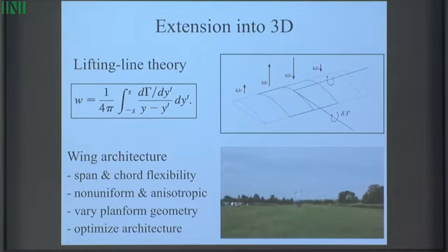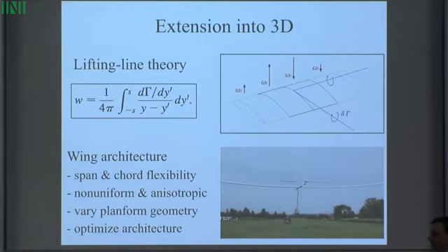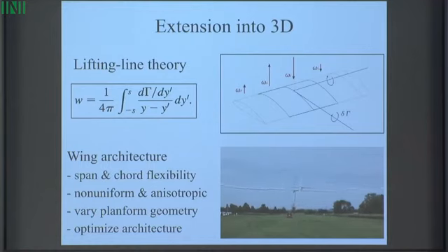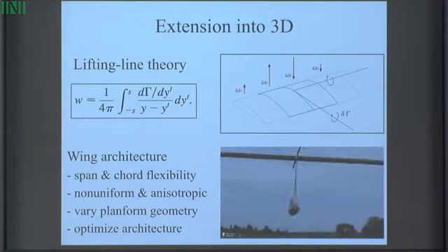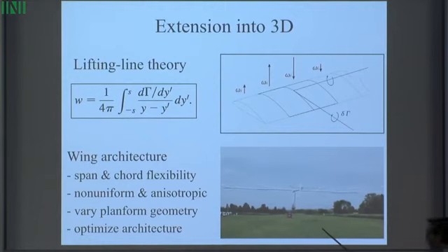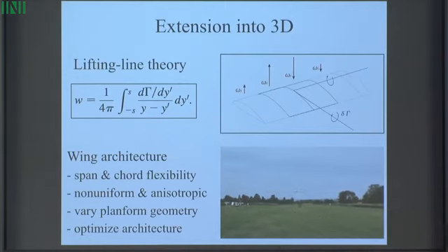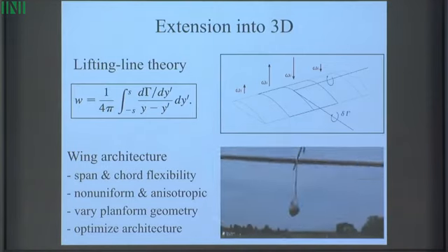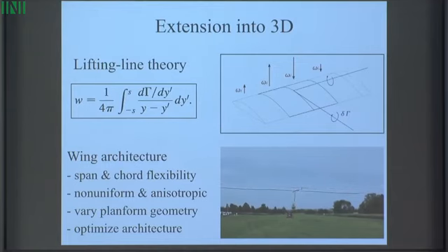You cannot get to the resonant frequency using classical lifting line theory, and you certainly can't get to that high frequency case where the flapping is out of phase. So what I would like to do is use the small asymptotic theory, but adapt it to 3 dimensions like this. And the reason is you'll be able to capture those different dynamical states. So you're not limited to quasi-steady.